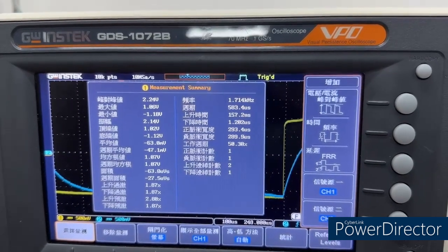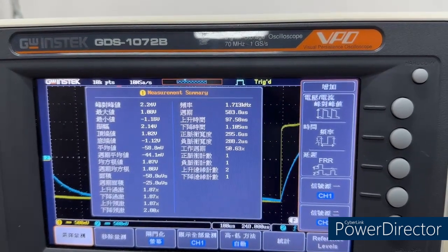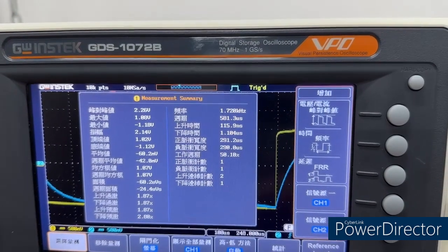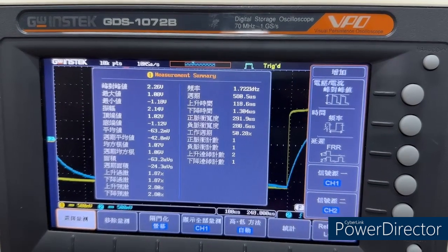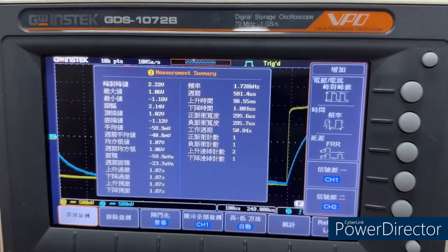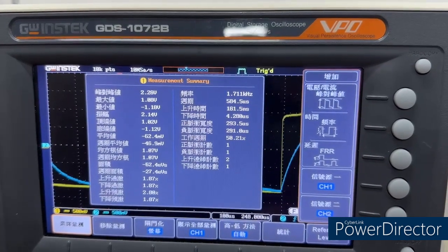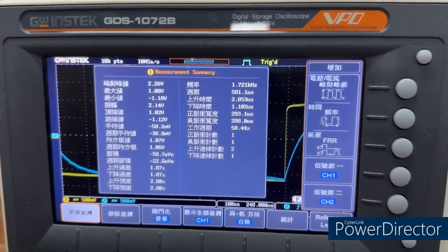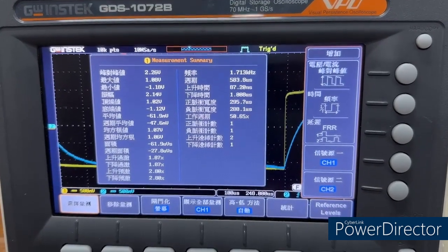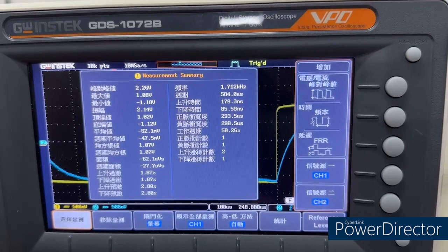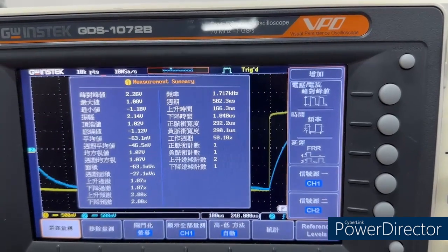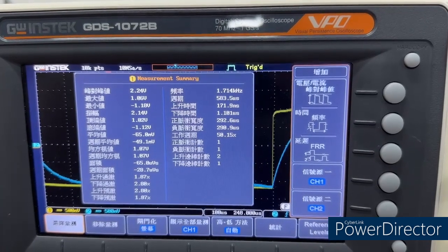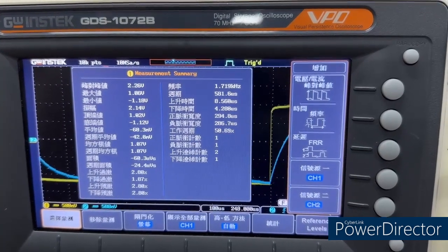Using the equation, we can calculate the voltage of the capacitor V0. At time equal to RC, which is the time constant, V0 will be 0.632 times the input voltage. So we can measure the time constant to get the value of capacitance.